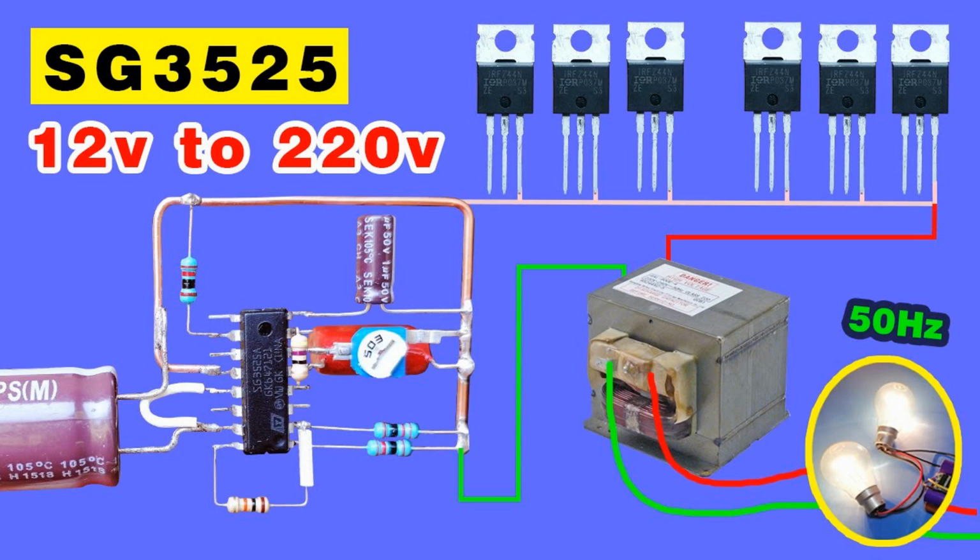Oscillators. MOSFETs are used in oscillator circuits to generate stable periodic signals. These are crucial in applications such as clock generation, signal generation, and RF transmission. Analog multipliers: used in applications like modulators, mixers, and automatic gain control circuits. MOSFETs enable the multiplication of two analog signals, facilitating complex signal processing tasks.